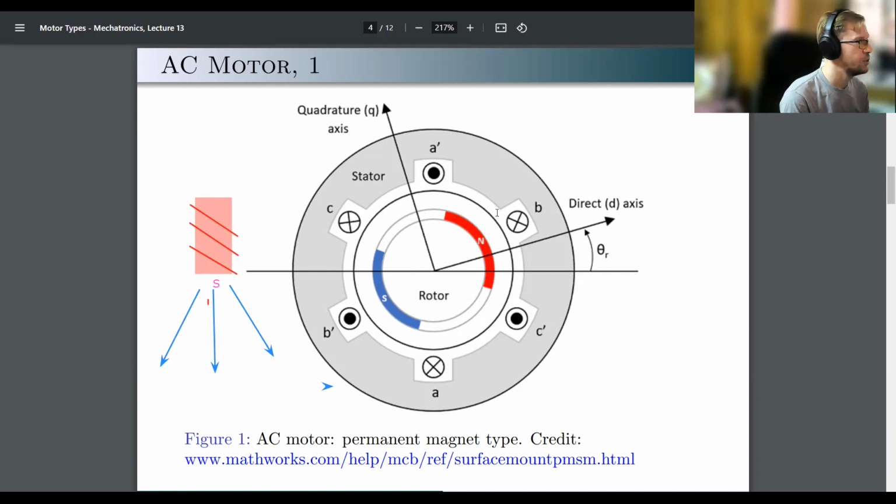Ultimately, what happens in a motor is that you have those coils spread around, which produce a magnetic field. They will produce either a south pole or a north pole magnetic field. Now, the rotor you can visualize as a magnet. If you remember how magnets work, if you put a magnet next to another magnet, they'll try to align.